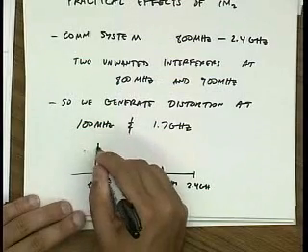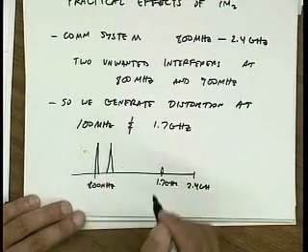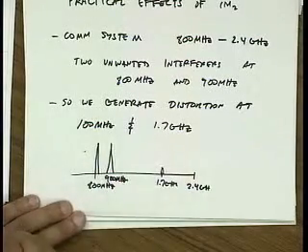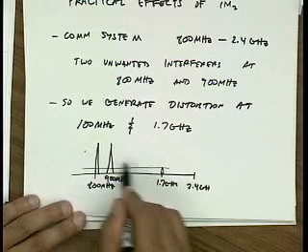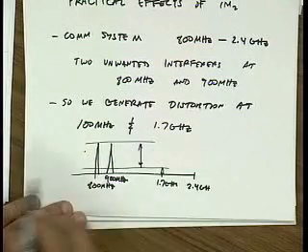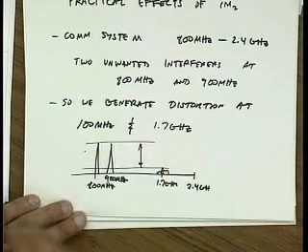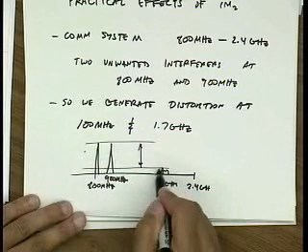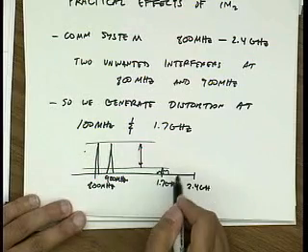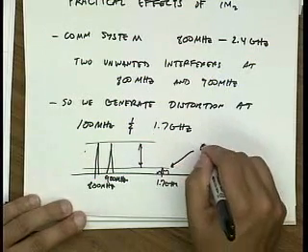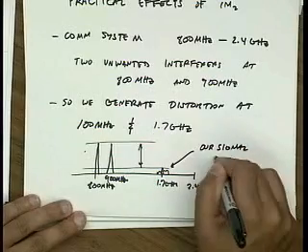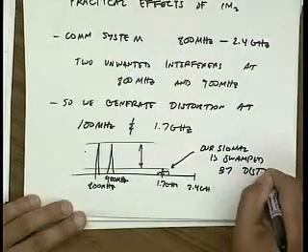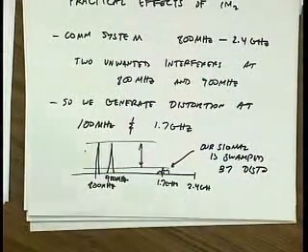And let's say that the people transmitting on 800 and 900 megahertz have very strong signals, right? Much bigger than your signal. So they're going to generate distortion that's going to fall in band. And even though that distortion is small compared to their magnitude, it can be large compared to your magnitude. So this could completely swamp out your signal. So our signal is swamped by distortion, potentially. Okay?